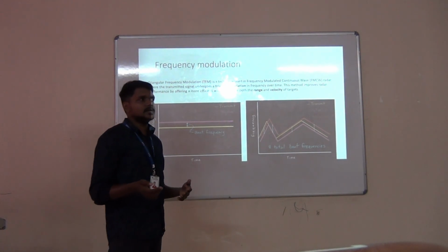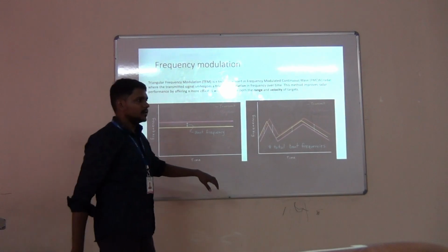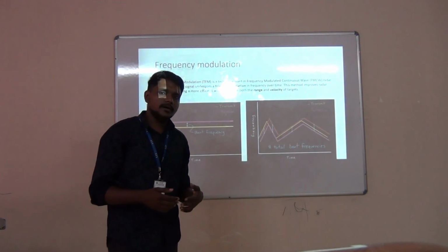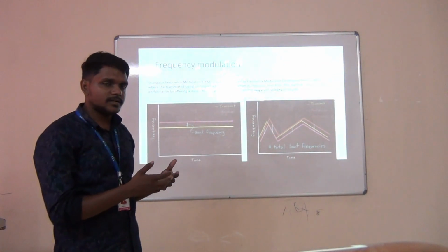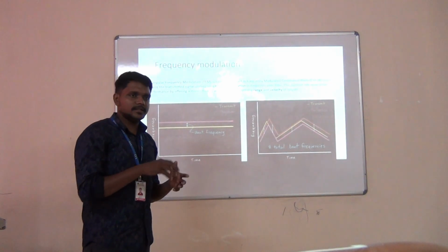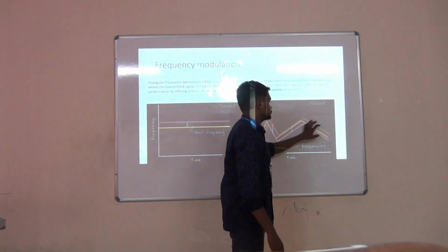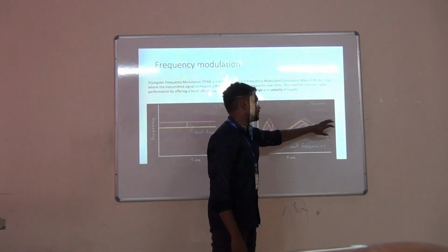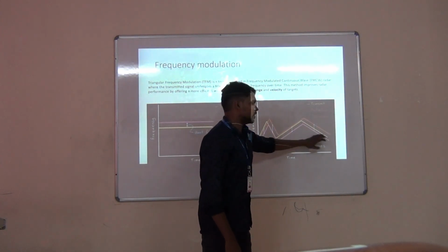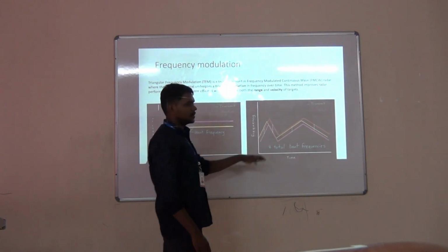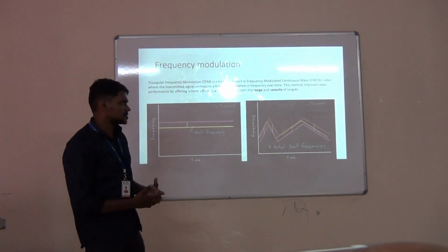So even if a particular car is moving and another 2, 3, 4 cars are moving, if we transmit and get a computed value, we can have an assurance that our ECU will detect whether the object is present or not. It will be better if we have multiple waveforms, like reflection 1 and reflection 2. Once the object is hit by the transmitted waveform frequency, the receiver frequency can be detected easily, right? So you will have multiple reflections.